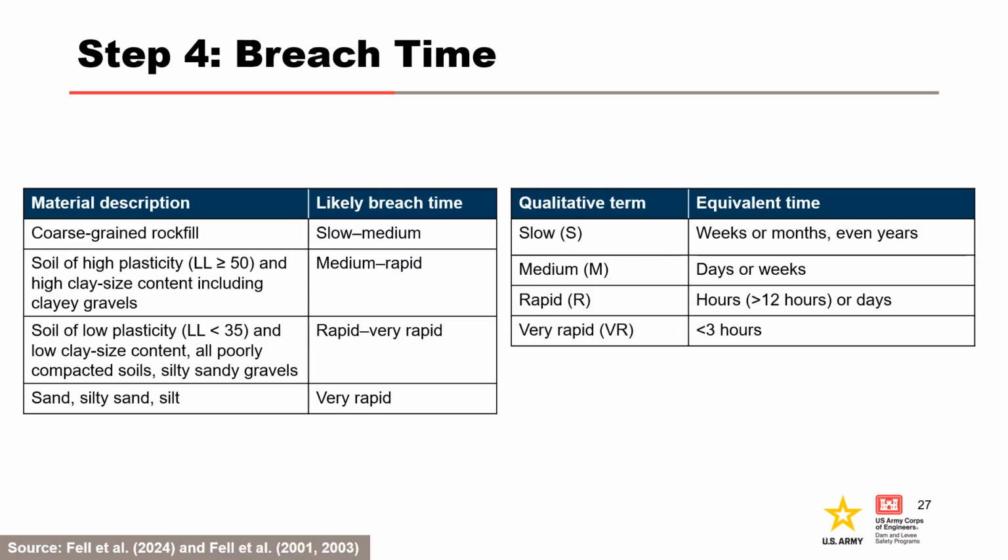Finally, step 4 assesses the breach time. These tables provide qualitative likely breach times based on material descriptions and then convert the qualitative likely breach times into equivalent times in hours, days, weeks, months, or even years. These qualitative terms are used in the approximate method.